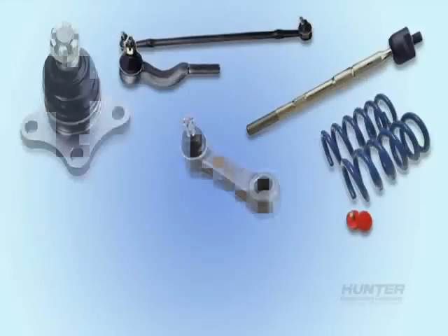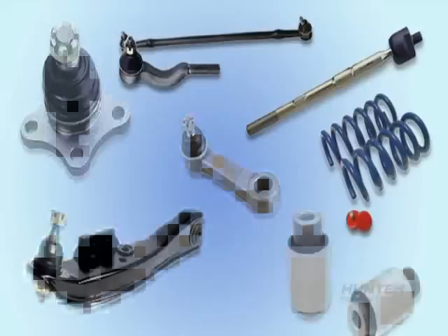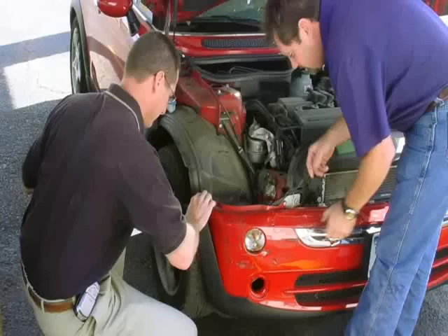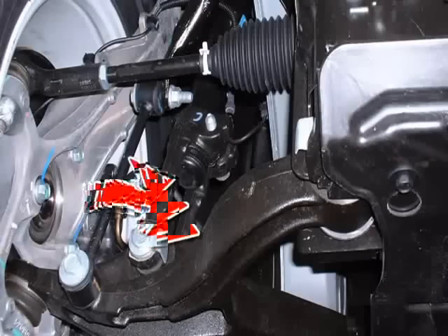And let's not forget about the rear of the car. The same slow decay is occurring there as well. The springs are wearing out too, and as the springs give way, so goes the alignment. Even though this type of wear is very slow, eventually certain parts may require replacement before the alignment can be done. Rapid changes in alignment are usually caused by impact or collision damage. The type of impact that will bend or move parts. For example, a control arm, a tie rod assembly, or even a shift in the position of the suspension in the chassis. Of course, damaged parts will require replacement.